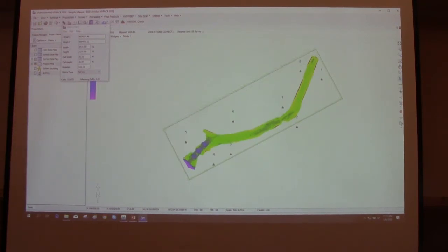I could go in here and enter cell length and width. They don't have to be the same, so you might want to do, I don't know, a 10 by 20 grid for some reason. Sometimes that works out better for single beam, because a lot of times you're going to be a lot further apart with your lines than you would with multi-beam for complete coverage. So you can play around with that if you require it. I think that was all.